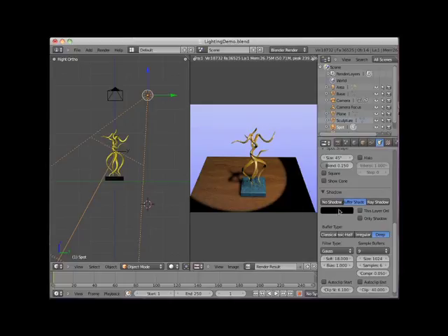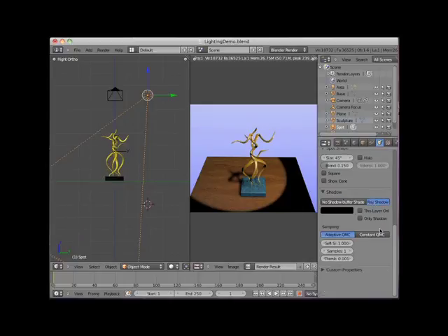I'll switch to ray traced shadows and render the scene. The ray traced shadow setting produces a very accurate and by default hard edge shadow. The ray traced shadow setting has two different methods for generating shadows, adaptive and constant QMC. The constant method is used to calculate shadow values in a very uniform, even and distributed way. This method results in a very good calculation of the shadow value, but it's not as fast as the adaptive QMC method. However, constant QMC is more accurate.